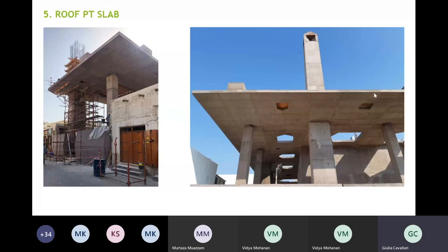From these pictures, we can see clearly the large cantilevers here and the floating effect of the slab above the column apex, and the large feature voids. These feature voids have changed throughout the project about 100 times. Their orientation and their location has changed so many times. But in the end, we came up with some standard details that could be applied based on the size of the void and could be repeated to simplify the life of the contractor.